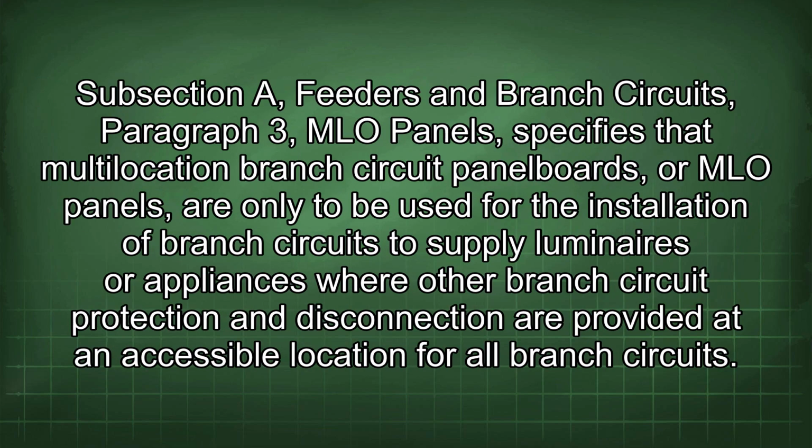Subsection A, Feeders and branch circuits. Paragraph 3, MLO panels, specifies that multi-location branch circuit panel boards, or MLO panels, are only to be used for the installation of branch circuits to supply luminaires or appliances where other branch circuit protection and disconnection are provided at an accessible location for all branch circuits.